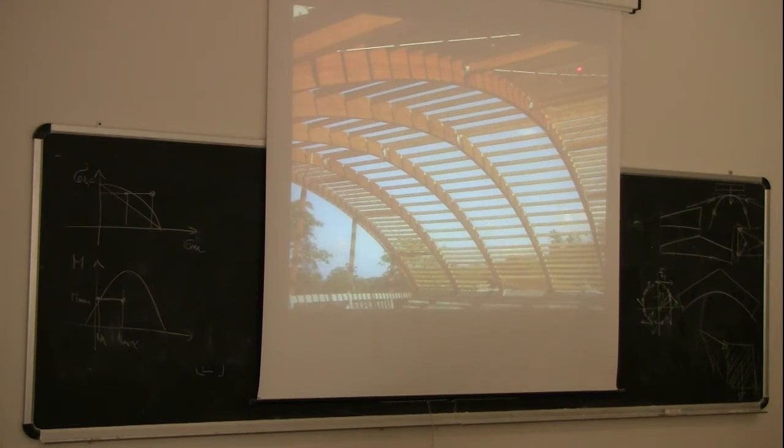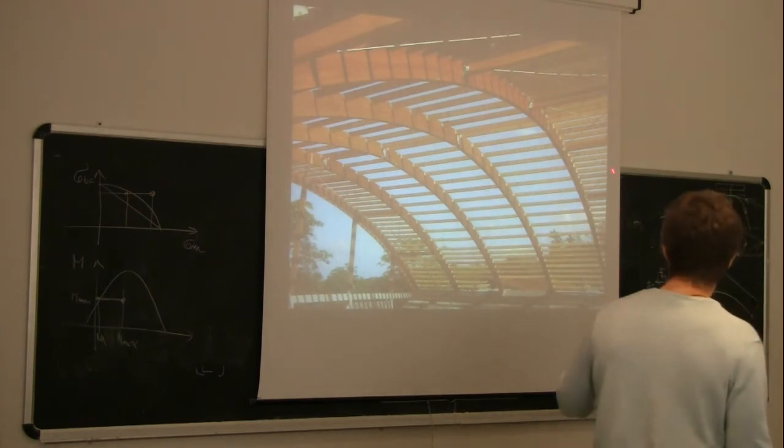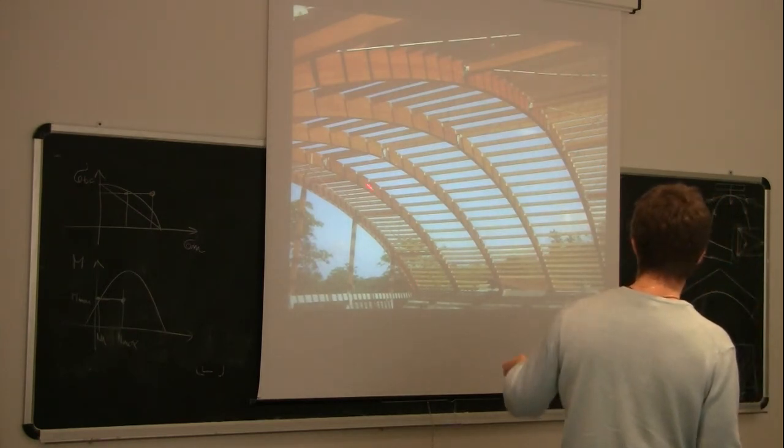You see there is some bracing made of steel rods. Where there is bracing, there is an additional purlin. As you can see here, we have the normal purlins, which are above the arch. And then we have an additional member just underneath, to take the axial forces due to the bracing forces. Here we have one bracing, here we have another bracing.